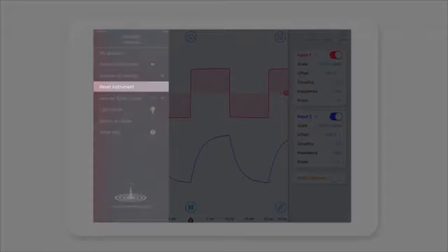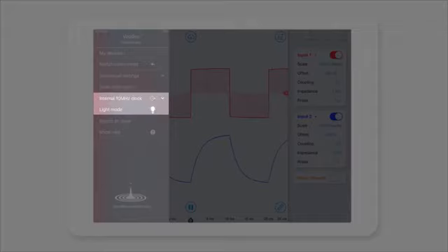We can reset the instrument back to default settings. We can configure the 10 megahertz reference. The only thing to note here is that by default, if you connect a 10 megahertz reference into your MokuLab, then it'll automatically switch to synchronizing with that external time base.